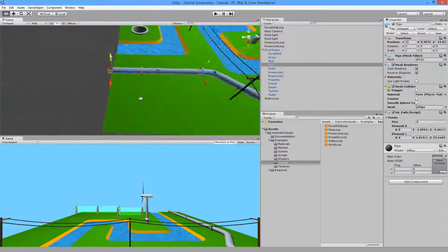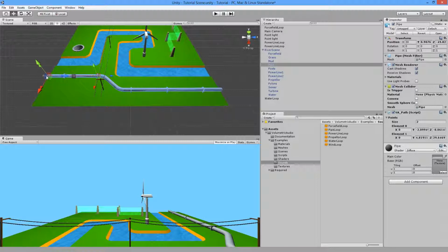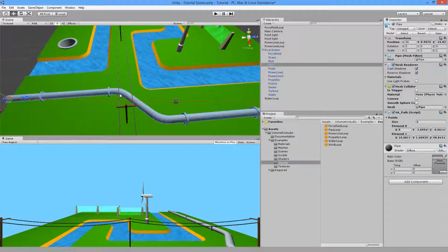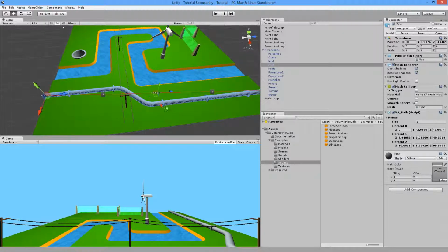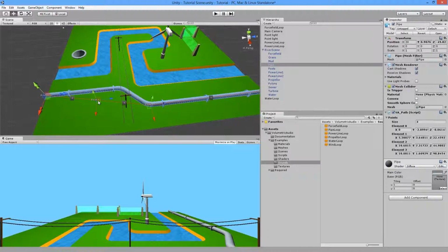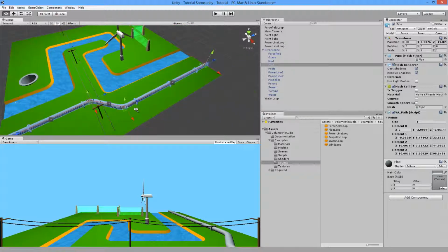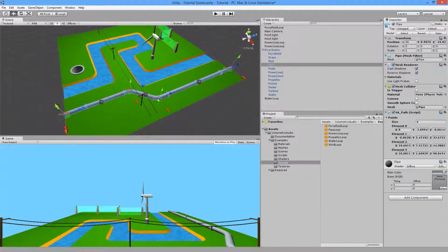So to set up this kind of pipe, let's leave 0.0 at the start of the pipe, and let's move 0.1 to the end. And you see we need an additional 2 points, one here and one here. To easily do that, let's click the plus button here to split the existing line. So now we add an additional point in the middle. Let's set that up so it's there, and let's split this path here. So now in total we have 4 points, 0, 1, 2, 3. And if you want to fine tune any of the numbers, then you can adjust them here in the inspector.